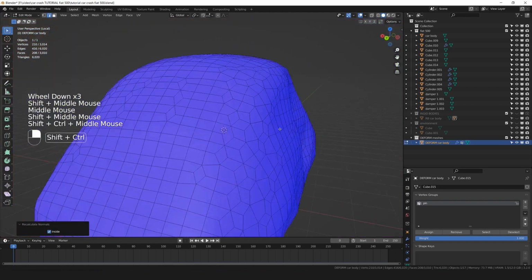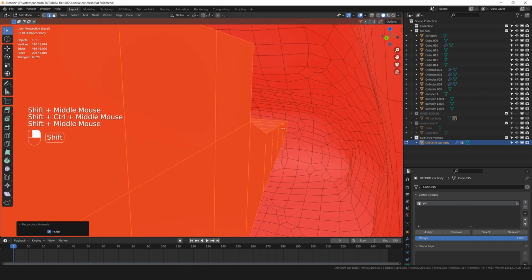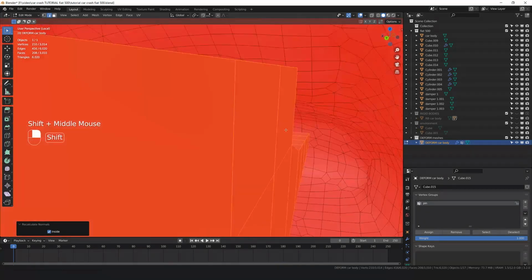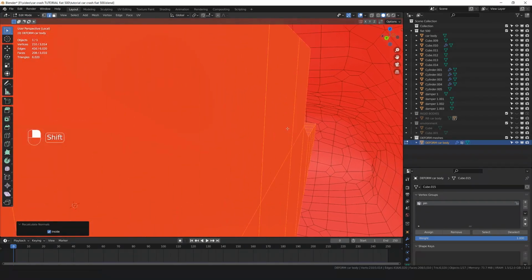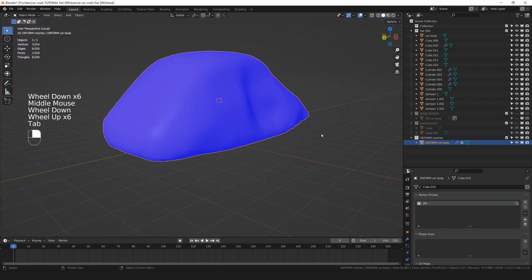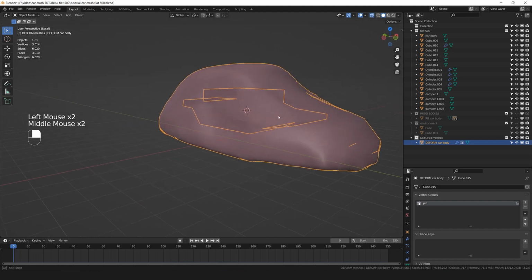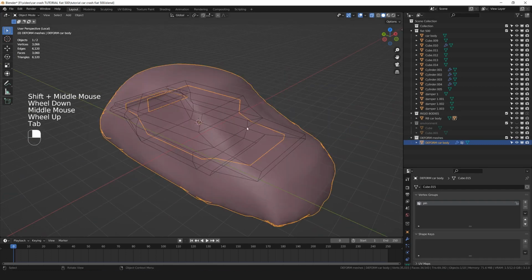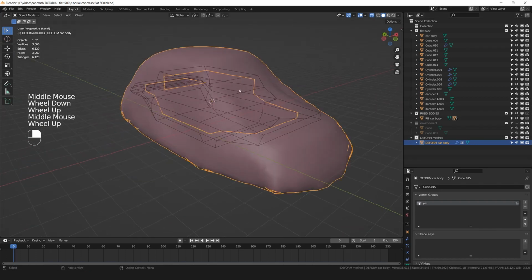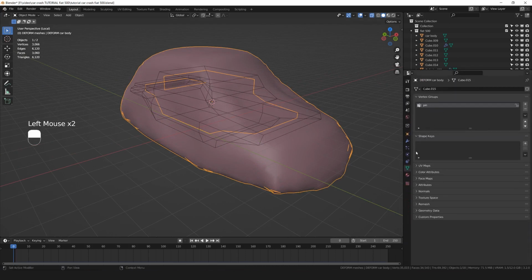So that now everything should look like this. Blue outside, and if you slowly go inside, this internal layer should be red, and when you go inside the internal group, everything should be blue. Now you're not gonna see any glitch in the collision for the cloth. Now, we can turn off the faces orientation, we can get back the visibility of the rigid body car. So, at the end of the game, we made all this process just for creating this pin group that finally we can link in the cloth options.